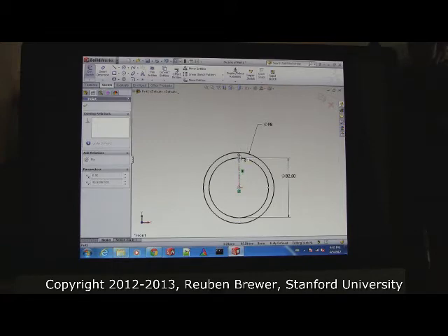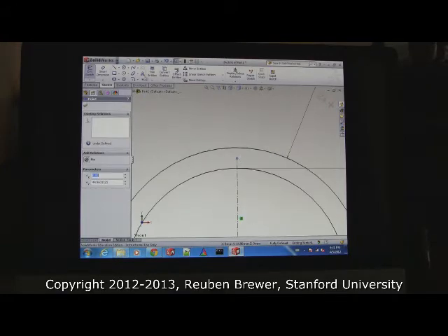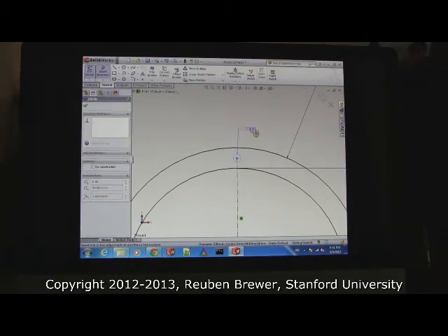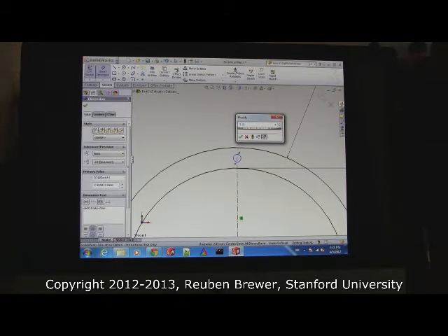How do you move the circle? You can't. It's locked to the origin now. We'll go over that later. That's a little bit more advanced. Okay, so everybody take a circle and put it at the tip of that line. It doesn't matter what the diameter is right now. Okay, now I want you to set that circle to 3.2. Okay?